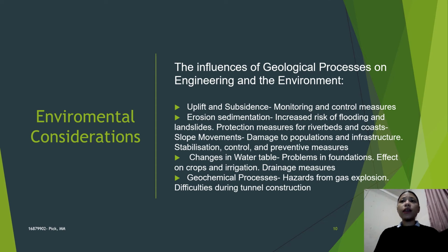Environmental considerations: the influences that the geological processes will have on the environment are the uplift and subsidence, which require monitoring and control measures; erosion of sediment, the increased risk of flooding and landslides or damage to populations and infrastructure; then the changes in the water table, which can cause problems in your foundation and affect crops and irrigation and draining measures as well; and then your geochemical processes, which are hazards of gas explosions or difficulties during tunnel construction.